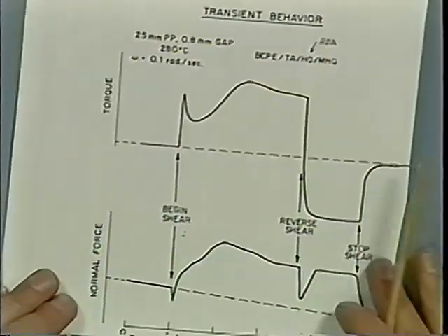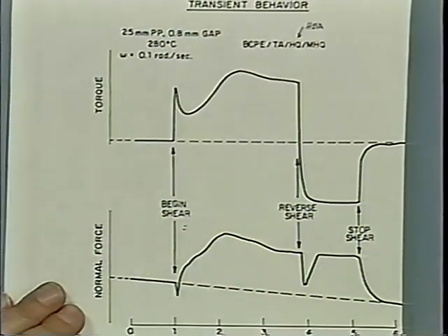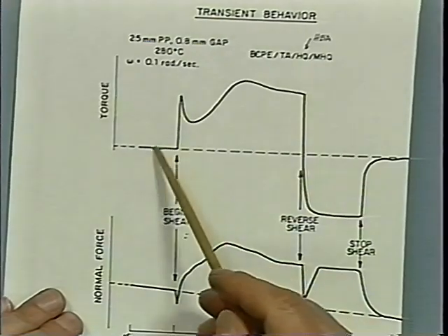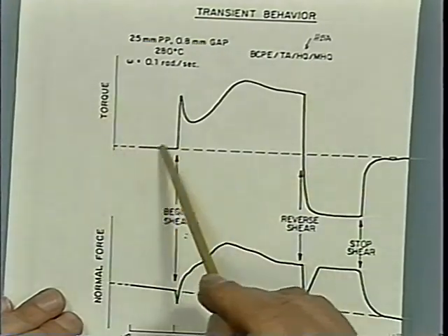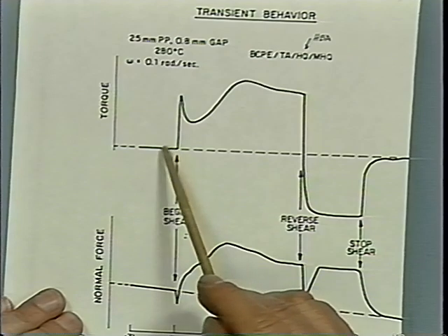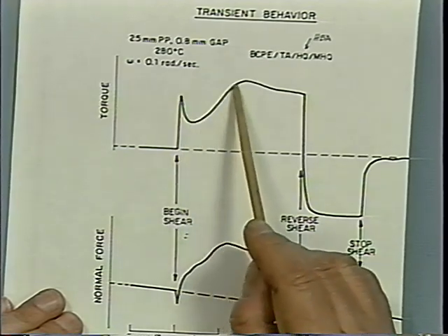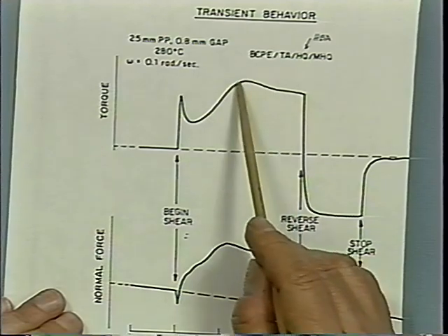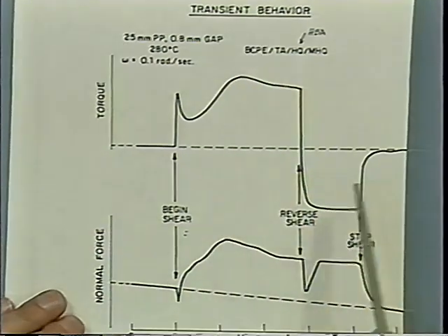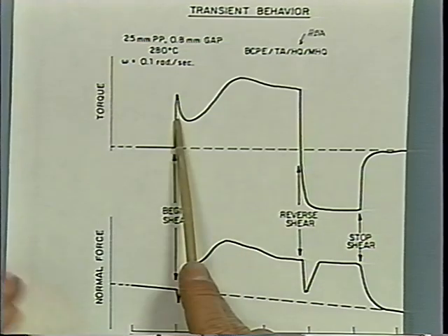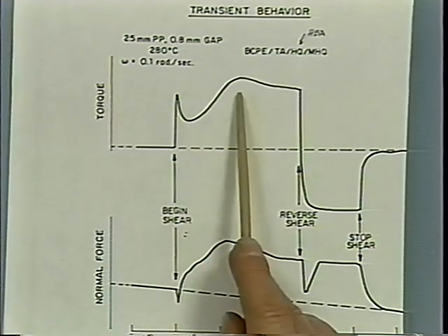Wissbrun, 1980, described the startup of a thermotropic liquid crystal. The shear stress is proportional to the torque, so we can say this is somehow shear stress related. It goes through an initial peak, breakdown of structure, and the stress builds up again, and then it doesn't stay constant, it somehow goes through a second maximum. Very often this first maximum appears at about 1 or 2 shear units, and this